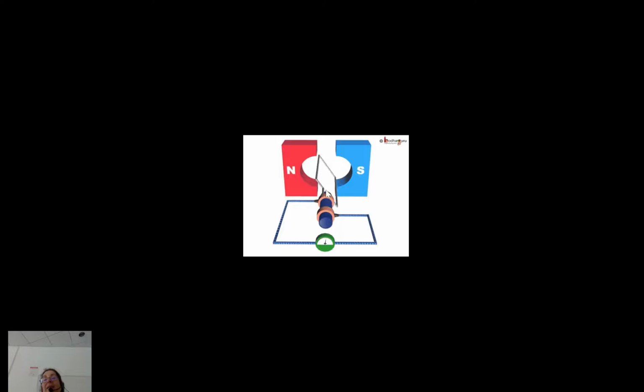You see the magnetic field goes from north to south, and you make it spin. Maybe you have a turbine, you have to make the turbine spin maybe with water or steam. You get steam if you are burning fossil fuel, and you see the number of lines poking through is changing with time. How fast it's spinning, meaning how many turns per second, that's going to be the frequency of the AC voltage that you are inducing. Isn't that amazing?